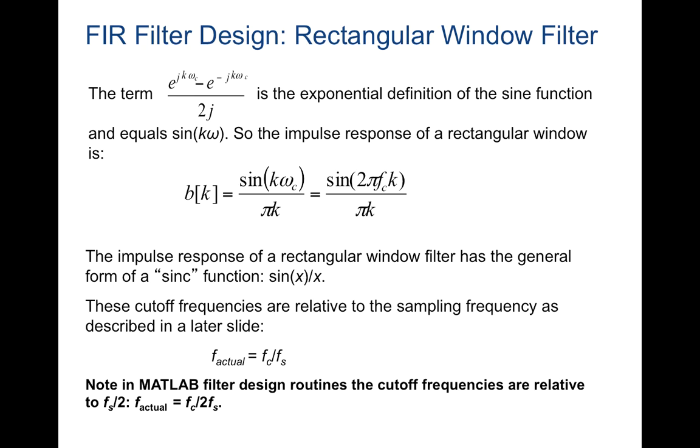The cutoff frequencies of the filter are relative to the sampling frequency. And so in MATLAB, it actually takes Nyquist into consideration. So your actual cutoff frequency is your cutoff frequency divided by 2 times the sampling frequency.